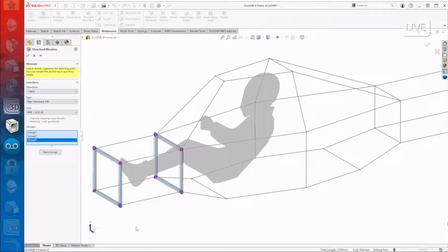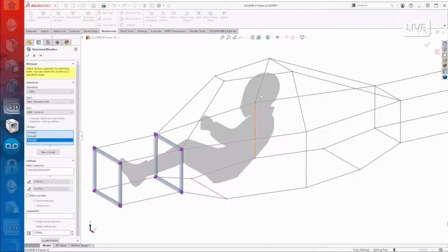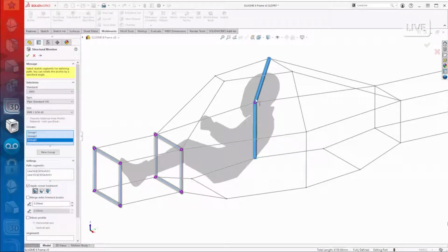These are called hoops. And you create the hoops first because they all need to be very robust connections to each other. In fact, the main hoop, this one right here that goes over the driver's head, is supposed to have fillets there. I just didn't add them because I was lazy, because that's supposed to be one continuous tube. And wow, they just bend the tube.